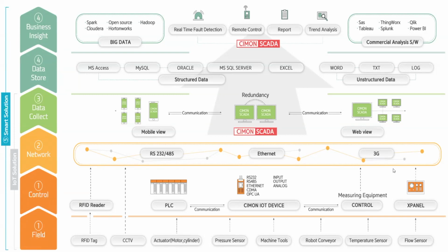So you don't have an HMI that's communicating with multiple plants, and you don't have a PLC that's controlling multiple plants. You have a PLC that's controlling devices that are local to itself. We're talking within a 100-meter radius, and the same thing for the X panel or the HMI. The HMI is coupled with the PLC typically, and it's looking to control a local vicinity of devices, like 100 meters. Now, that information that it's all gathering can congregate at a SCADA software or an IPC, which is sent more than 100 meters away, right?